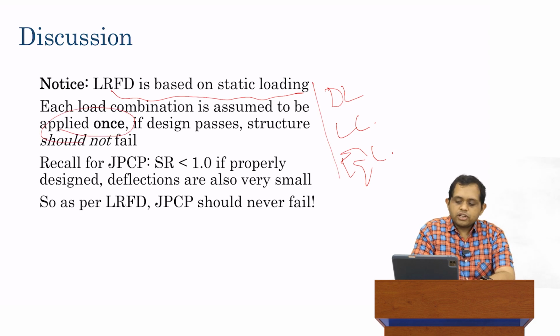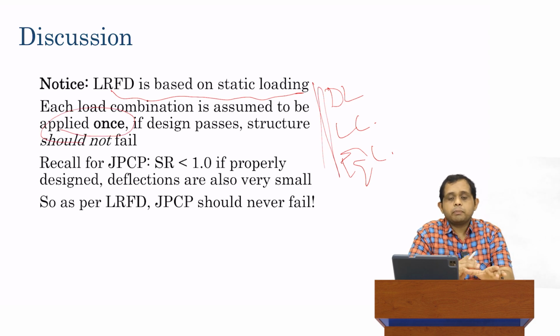That is, any combination of these different loadings, we apply it once. If that combination generates a stress which is less than the factored strength, then the design is successful. So we do not have repetitive loading. We have one loading applied once. If it passes the criteria of failure, then we say that the design is successful.